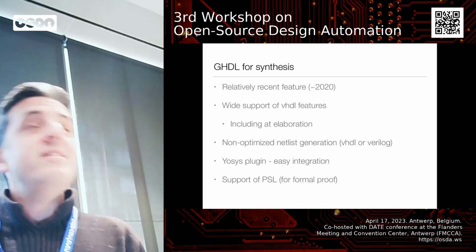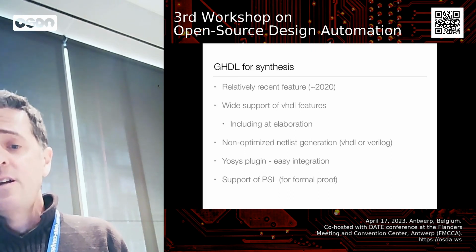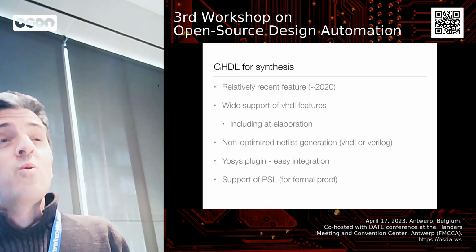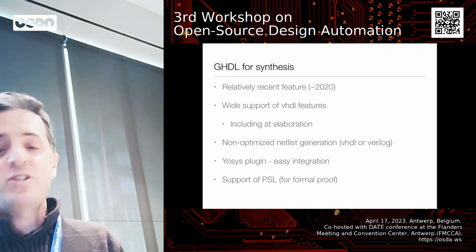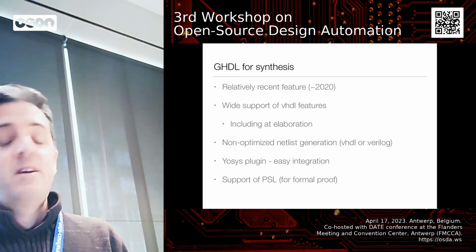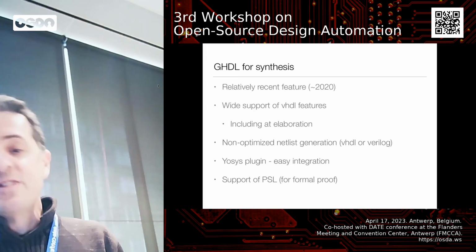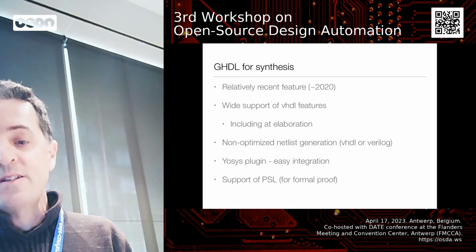Recently, well, maybe a few years ago, I added synthesis support for GHDL. What we have to understand is that it only generates a netlist which is completely unoptimized, and generates either a VHDL or Verilog netlist, and then it is integrated with Yosys in order to do optimization of this netlist.